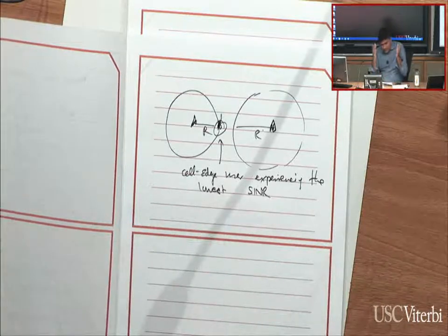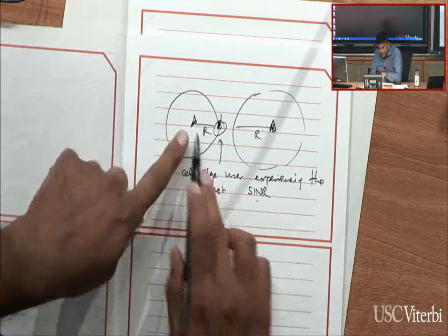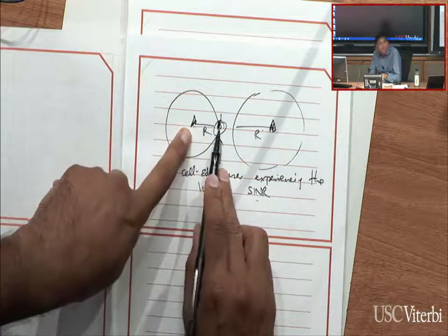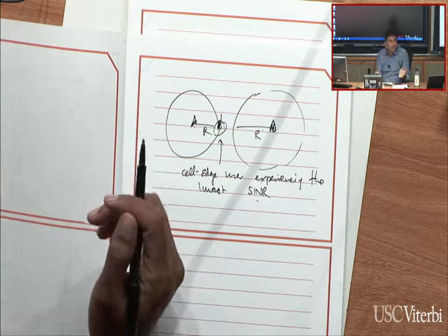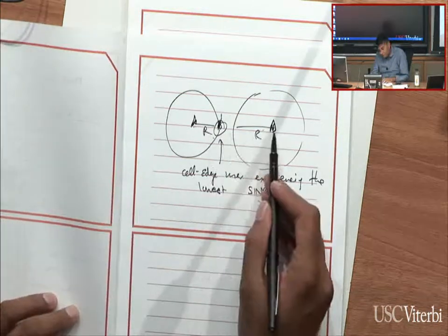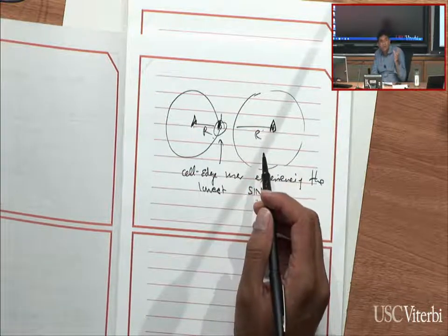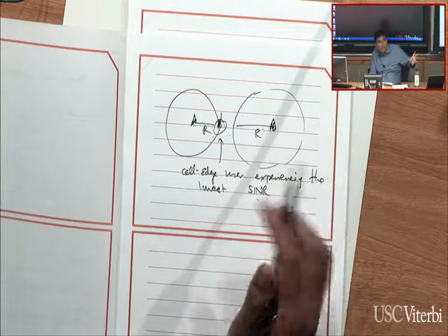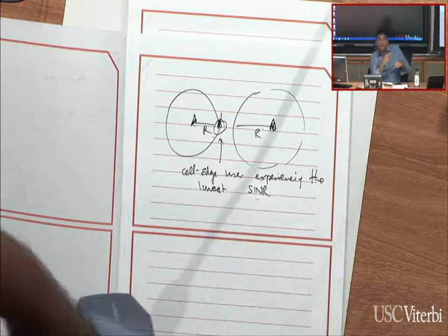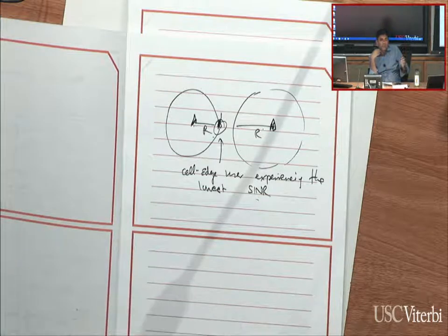Okay. So what can happen? If the channel quality is not just the mean value but also varying, the worst SINR it might experience is that the signal quality from the base station is not good. You're experiencing a fade, which means that from that distribution, instead of getting the mean value, you're getting significantly below the mean value for the signal. And likewise, from the interfering base station, for the worst case scenario, given this statistical variation in the signal, you might experience at some moment a very high value of interference. So on the one hand, just from the distance alone, you might be getting a certain SINR mean value. But on top of that, the signal might be below its mean value, the interference might be above its mean value. Under different circumstances, the signal will have different values, the interference will have different values, so the SINR is going to have different values. The SINR itself is going to be a random quantity.